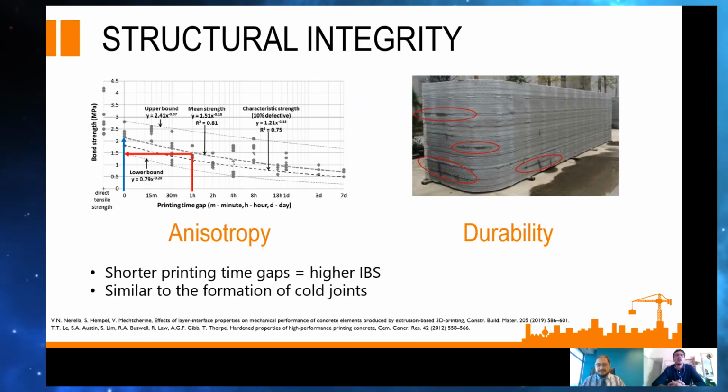However, in the mechanical state, due to the sort of layered structure, because we're stacking layers upon one another, we have anisotropic material behavior. So it's not the same in all directions. So you require orthotropic material models to simulate the structural response. So in one direction, you'll have different strength. The direction that is directly over the interface. So if you look at the structure on the right, if you were to pull it, say, to the top of the page and to the bottom, it would be weaker than pulling it from left to right, due to the orientation of the filament layer.